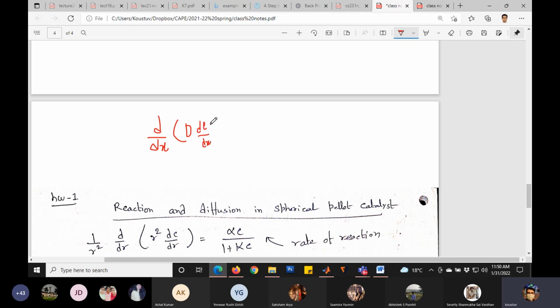So D, the second order ODE, and concentration, let's say just a simple boundary condition at L equals CL. So we can get a good distribution of the concentration. D is the diffusivity, which can also depend upon concentration, linearly or non-linearly, and like the previous thermal conductivity K, we can solve the problem in the same manner. So this case is basically diffusion across a flat slab.